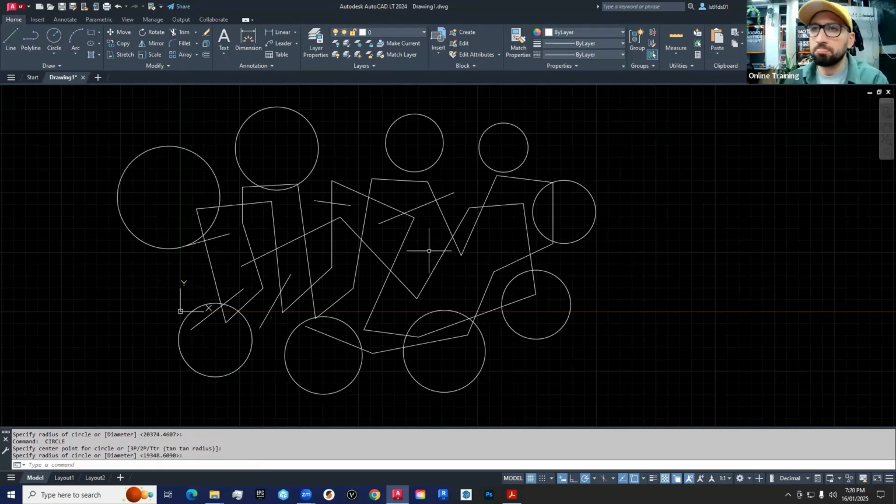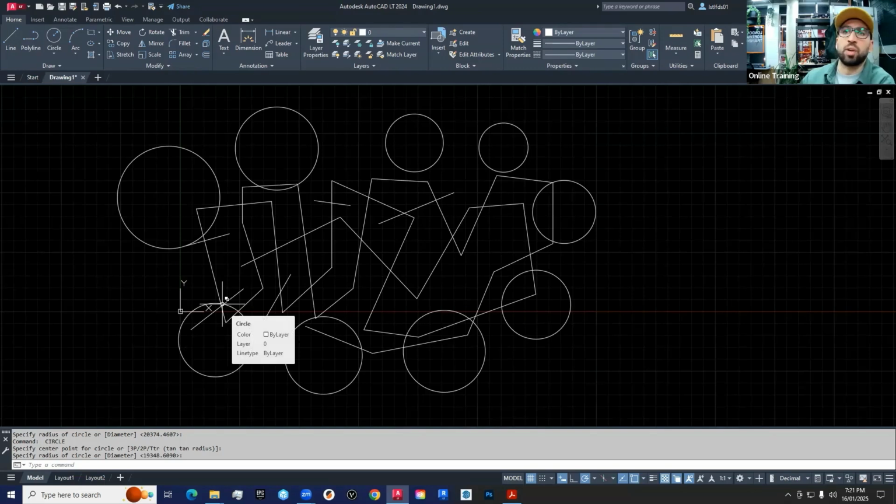And there you go. We work in a 2D coordinate system. So the corner you see right there is the origin, the 0,0 X and Y. So if you are on the top right side of this one, you are just in the positive X and Y quadrant or region, which doesn't make much of a difference unless your project is linked to a survey drawing on site or linked to coordinates. But otherwise, just feel free to draw anywhere.